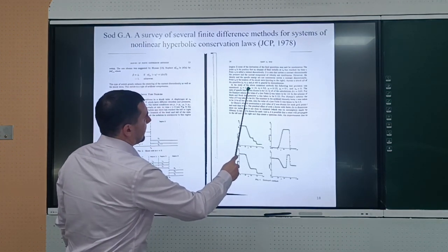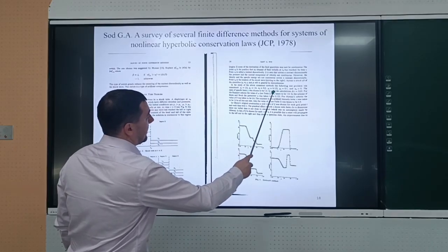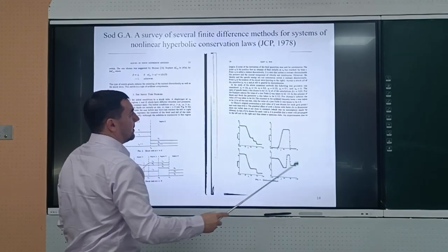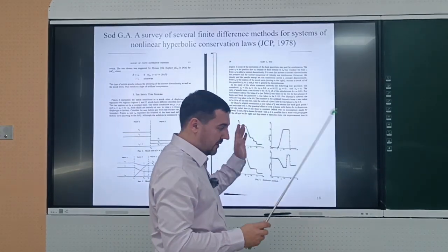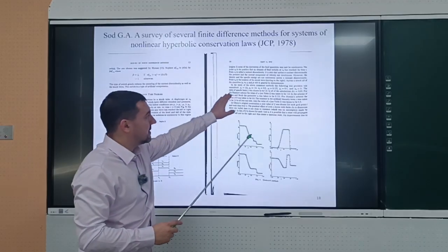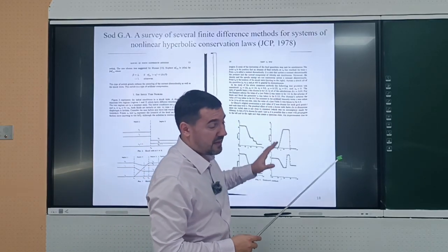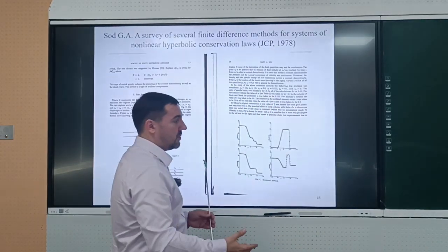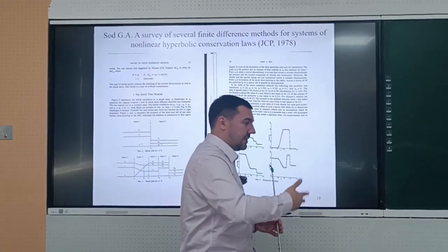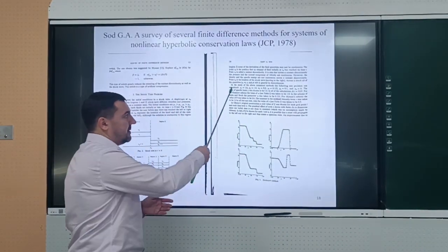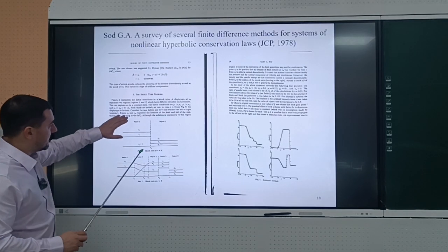Density to the left 1, pressure 1, and velocity 0. And to the right, density 1/8, pressure 0.1, and velocity 0. So he just suggested these parameters; they do not correspond to anything. And they are all dimensionless, so do not think that it's in pascals or kilograms or meters. For example, if you have atmosphere, you can choose some scaling, so that your pressures are in atmospheres, and then you can divide by 10 to the 5th power and you will get unity. So just dimensionless parameters.